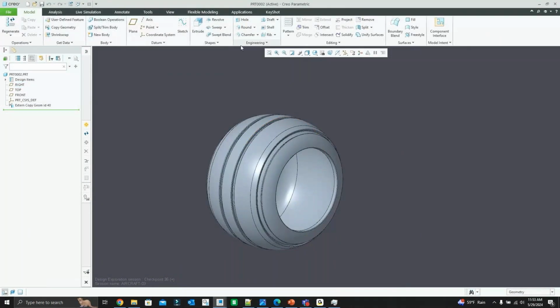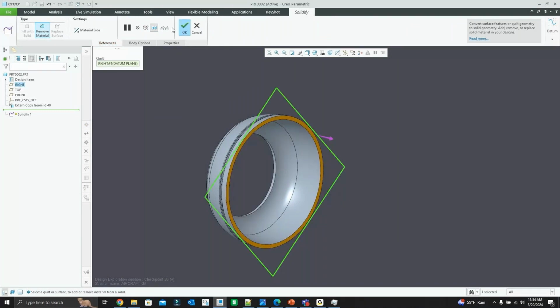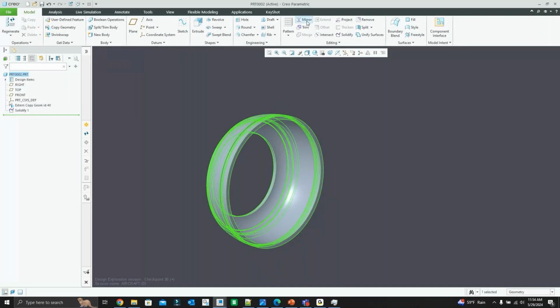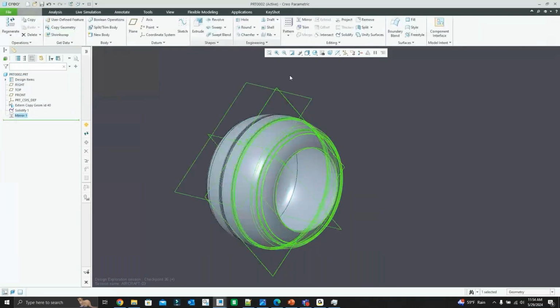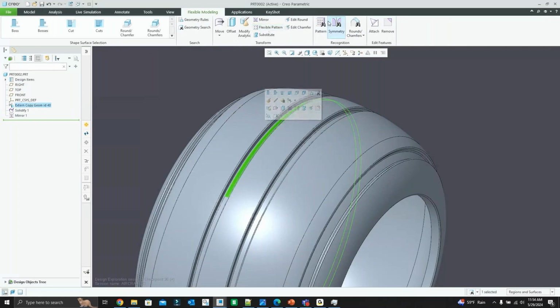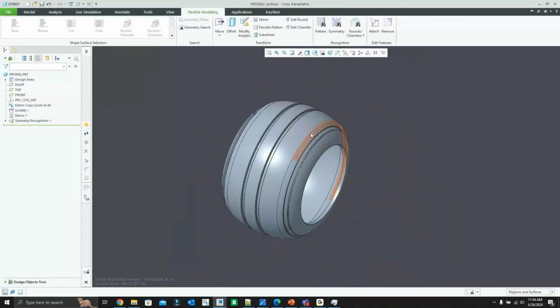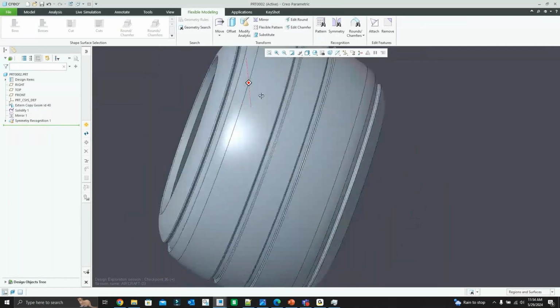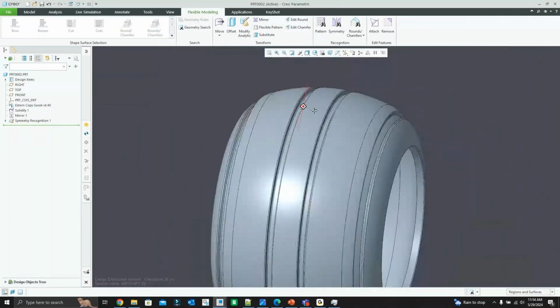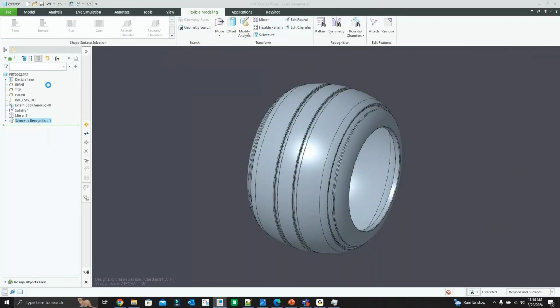Okay, so what we'll do is, let's see if I just solidify it. I'm going to split it, and I'll just mirror it over. Let's see if it finds it now. There we go. Okay. So for whatever reason, there's a little bit of a quirk there, because it's supposed to just allow me to identify that mirror, but I basically created that in here, then it recognized it in the part. So we should be good now. It recognized that symmetry of that part.